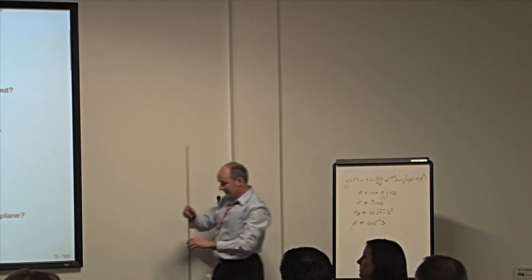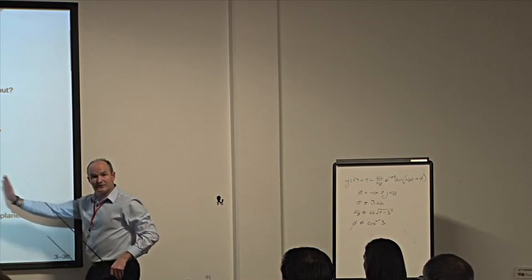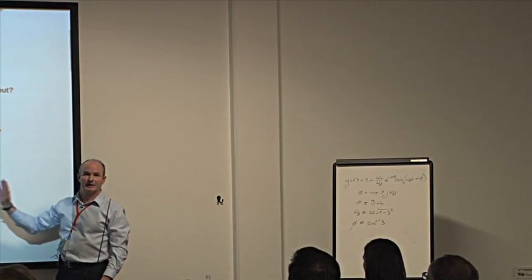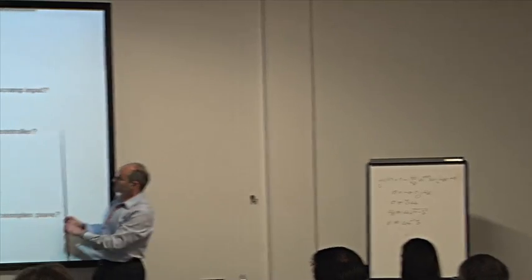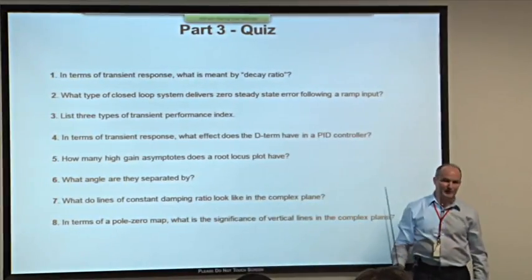And remember, it's equivalent to saying that as you move further to the left in the complex plane, the step response decays more quickly. As long as you move them to the left, it's the decay parameter that's changing.